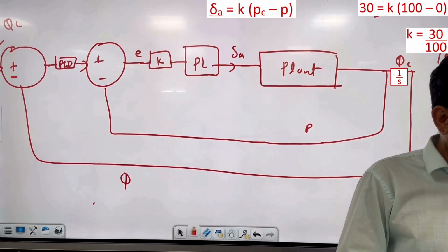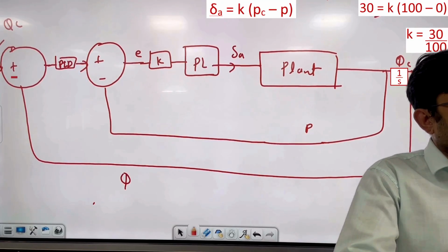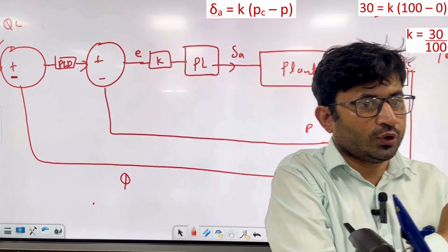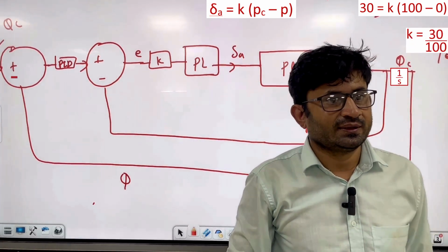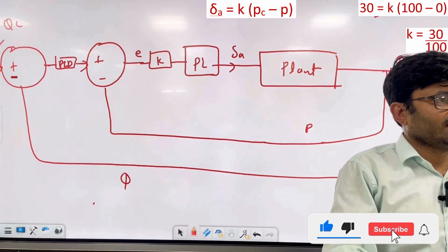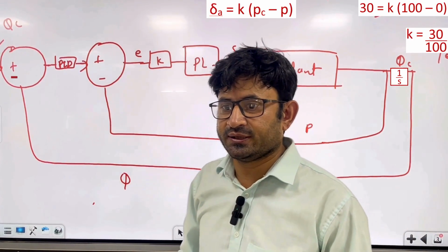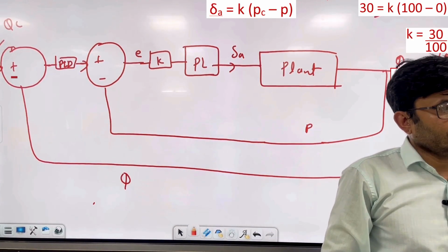I mean to say, when you give throttle, you increase the power, and with the excess power you will climb. So you will not have any automated control on altitude basically, right? Altitude is still changed by increasing or decreasing the throttle. Increasing, it will increase, putting the throttle down, altitude will drop.